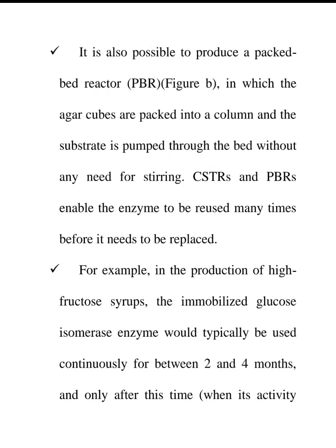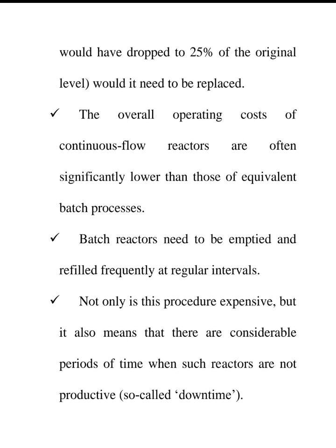For example, in the production of high fructose syrups, the immobilized glucose isomerase enzyme would typically be used continuously for between 2 to 4 months, and only after this time, when its activity would have dropped to 25% of the original level, would it need to be replaced. The overall operating costs of continuous flow reactors are often significantly lower than those of equivalent batch processes.